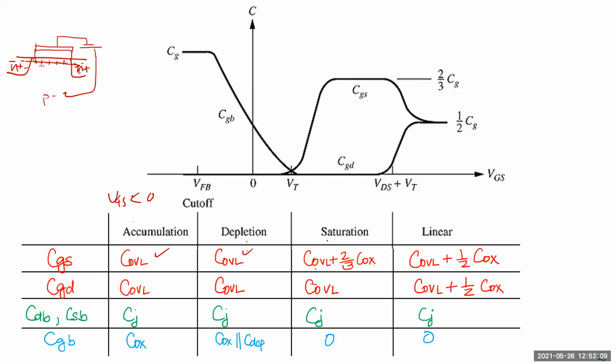And that's not part of post layout. In post layout, you have fringe cap of the vias. I think when I was doing this, it was Sandhya who asked what about the capacitance from the via to some node? Those are there, the small caps, but they will be captured as part of your post layout parasitic cap. Okay, any other question?